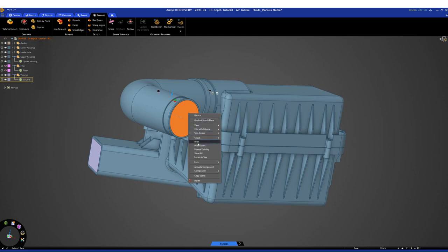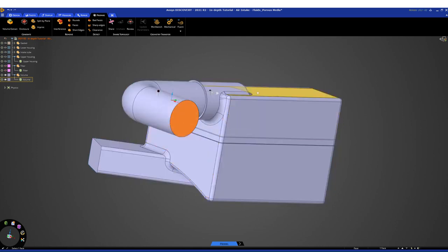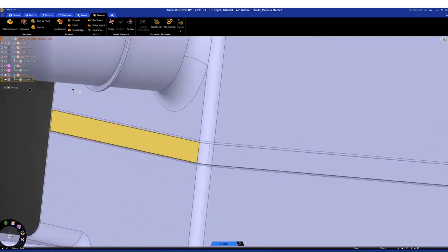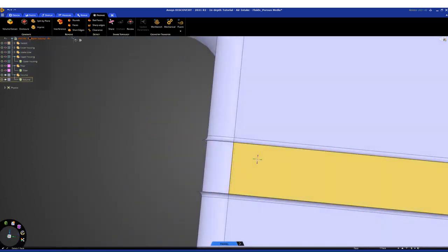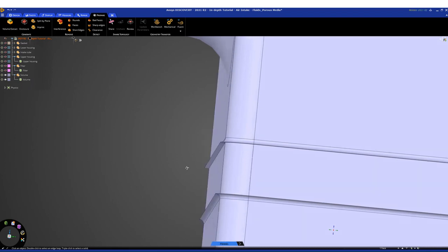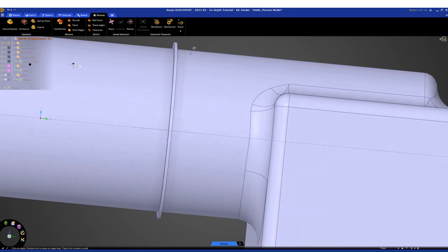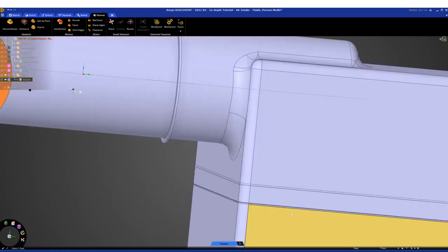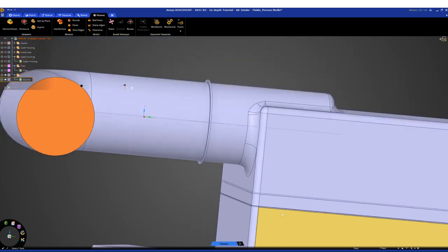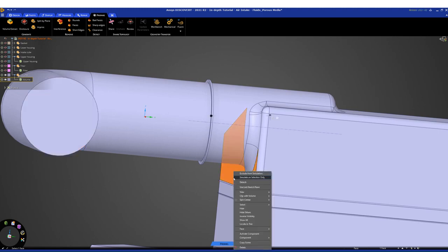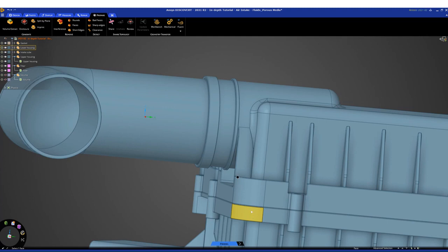So let's take a closer look at this fluid domain. We find now that we have some imperfections of the fluid here. I mean, sharp edges that we don't want to include in the simulation, and this small cavity. By editing the original geometry, we can update this fluid domain afterwards. So I will show you that. We can just inverse the visibility of this.